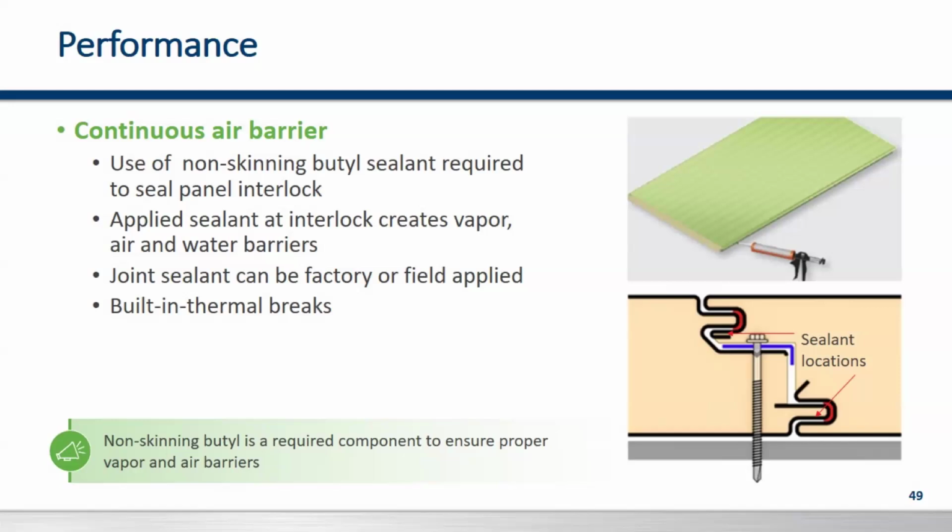You're also going to provide it in the pigtail location, which would incorporate where the sealant is between the frame of the building, the IMP panel, in that interlock, and the continuity of all three locations. When we do that, the building is virtually airtight. So we can truly make an airtight building when properly installed.